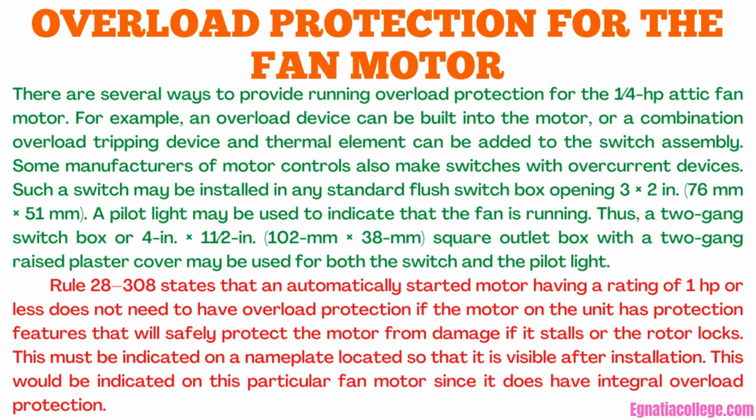A pilot light may be used to indicate that the fan is running. Thus, a 2-gang switch box or 4-inch by 1.5 inch, 102 mm by 38 mm square outlet box with a 2-gang raised plaster cover may be used for both the switch and the pilot light.